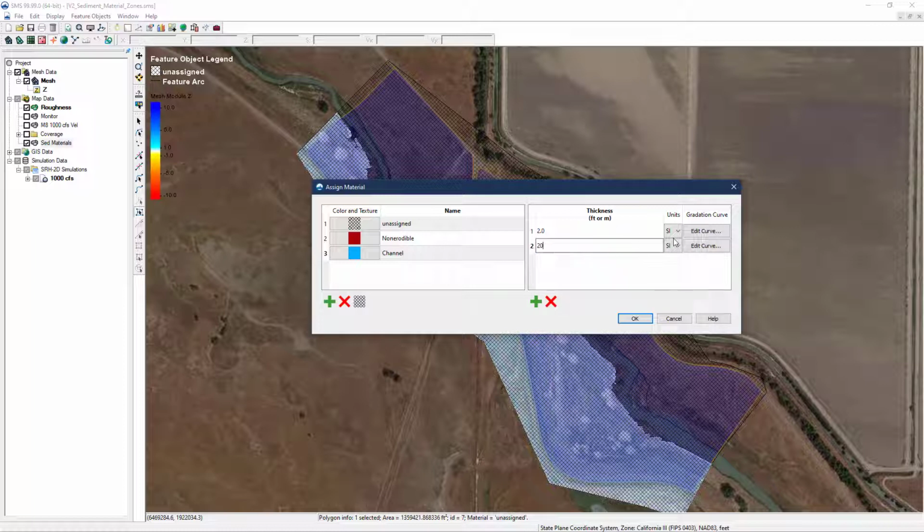Be sure to select the appropriate units for the layer thickness. The total depth of layers should exceed the full amount of anticipated scour, because the model will not indicate that the full depth has been reached, and instead assume that beneath the last layer is a non-erodible boundary.